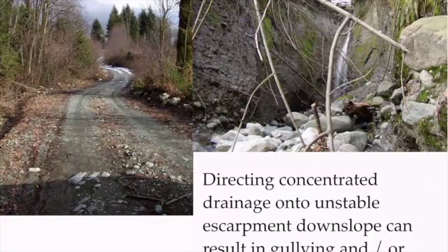So this particular road segment looks innocuous and benign. However, the way the water is generating and where it is being sent is creating a huge gully feature that is producing in the order of between 500 and 1,000 cubic meters of sediment each year. This is going directly into salmon-bearing portions of Dakota Creek as well. So this, by about tenfold, is more important than anything else that is happening in this watershed at this time. However, it might not be recognized if you just drove along the road without considering how much water is flowing in the ditch lines and where that discharge might be going.